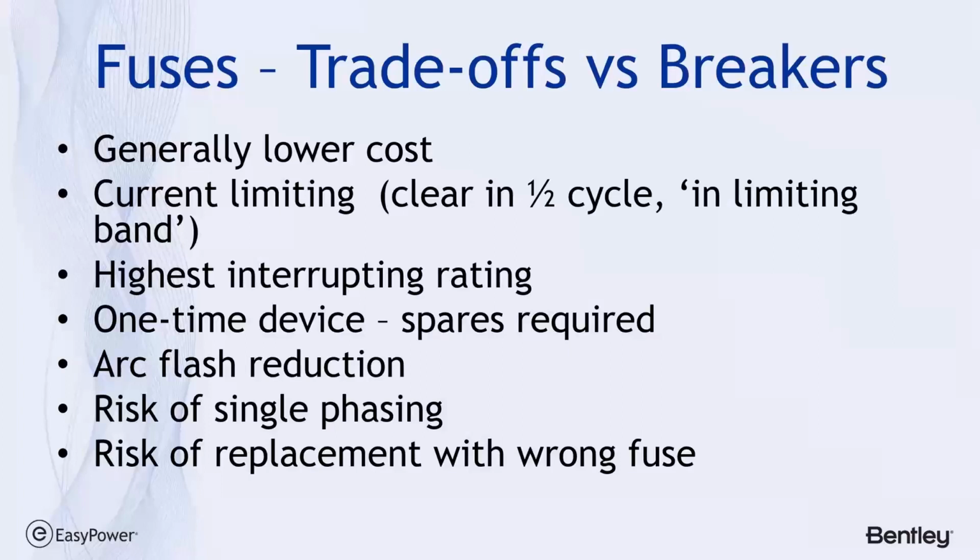In fact, that's one of the reasons when you do an update on arc flash data collection, you want to make sure you're checking all the protective devices, and in the case of fuses, making sure all three are the same manufacturer and part number and size. Just an aside.